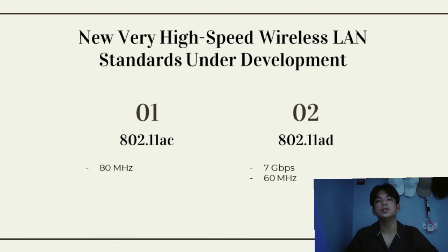For the second one, we have 802.11ad. 802.11ad is also under development. It targets accomplishing transmission speed of roughly 7 Gbps. It operates using a 60 GHz channel designed for shorter transmission distances, likely to be restricted by walls, and manufacturers are looking at 802.11ad for Wi-Fi based phone communication and HD movies on big screen wireless TV.